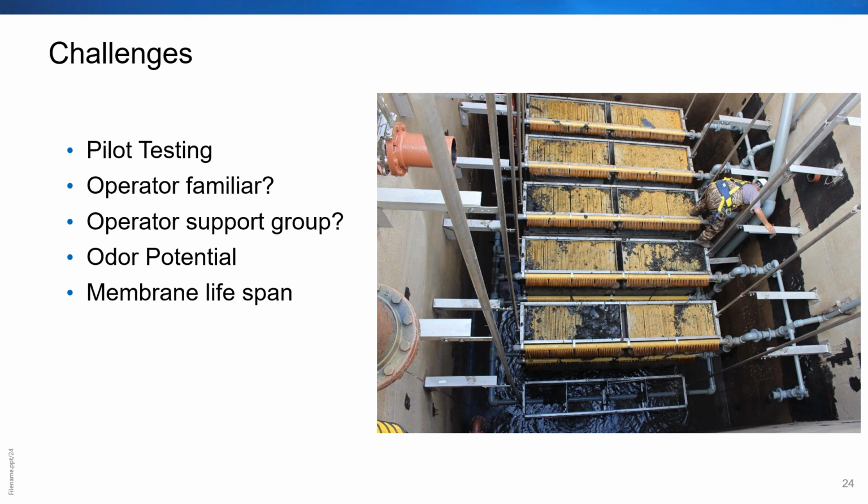As far as operator familiarity, especially for these small industrial plants, it's one thing to put in a treatment plant for them, and another thing to put in a high rate, high technology treatment plant. How familiar are they going to be, and do they have the tools to run that kind of facility? Similarly, who's their support group? On the MBR side, conventional activated sludge side, whatever it may be, you can find several folks, in Arizona or any state, that have these kinds of facilities. But when you get into something with less user base, who is the support group for these operators? That's something to consider.